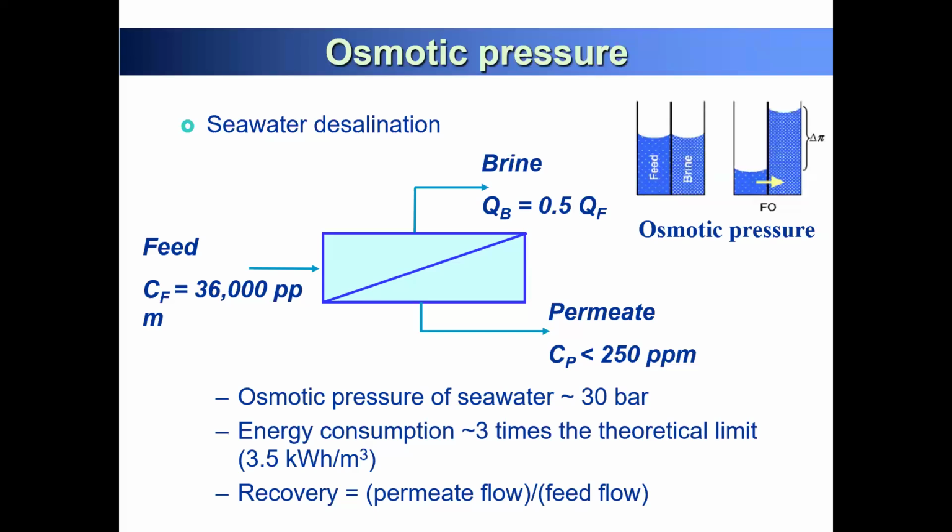So osmotic pressure is very important, and we have to know the osmotic pressure relationship between the feed water and permeate, and you achieve 50% recovery.